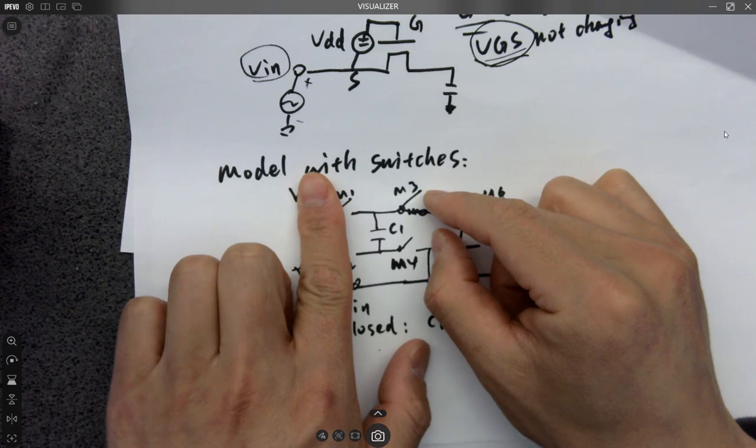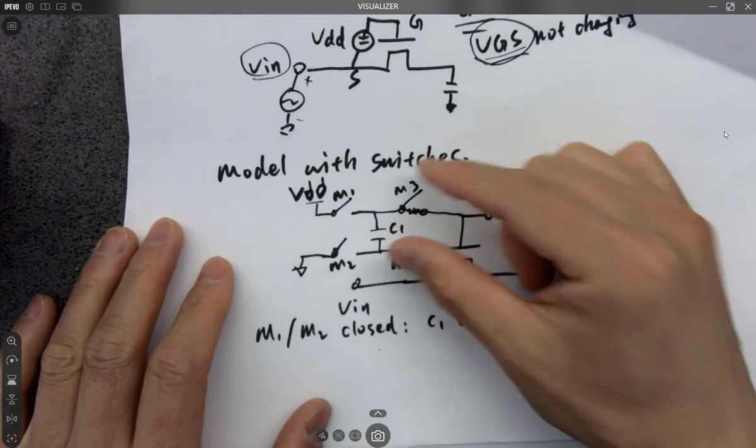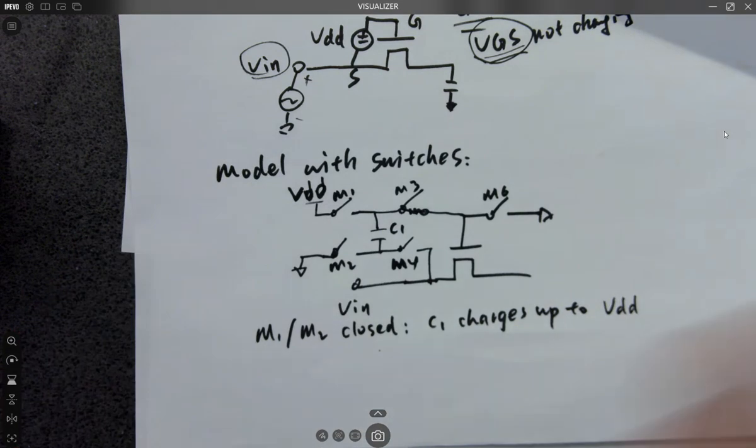And then you open it, so this cap becomes a capacitor which holds floating charges. It's just stored in the capacitor without being discharged to anywhere. Like, close, charge it up, open the switch. So the capacitor is able to hold a VDD across it. Okay? It's trapped in there. It's not going anywhere.